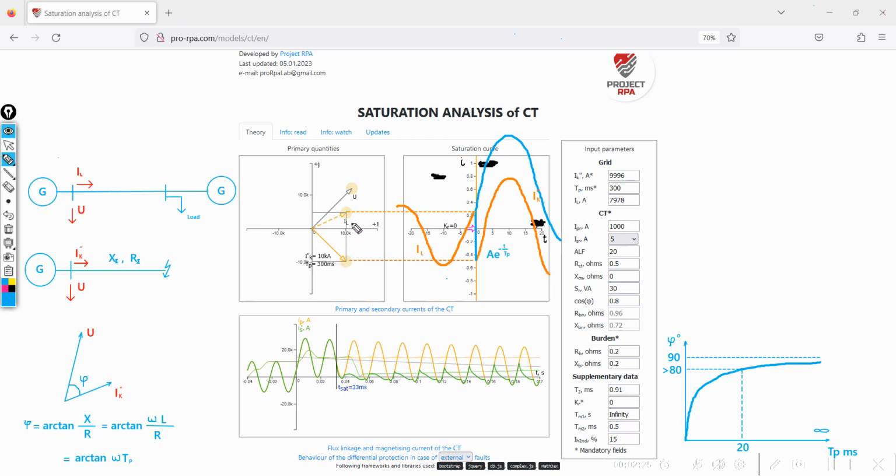Therefore, it is clear that for the largest initial value of the DC offset, the fault inception angle of the voltage must be rotated in such a manner that the two projections, that is, these two lines, coincide. In the sinusoidal curves below, this maximum value can be seen on this narrow line.